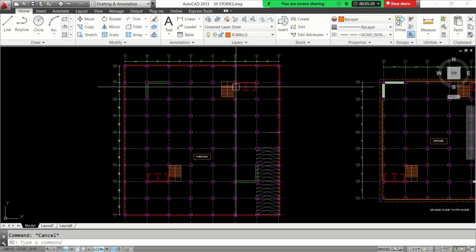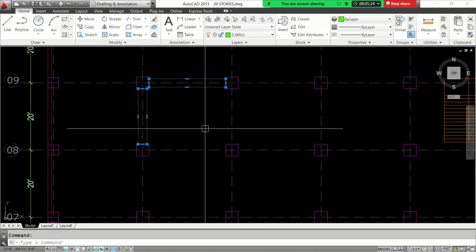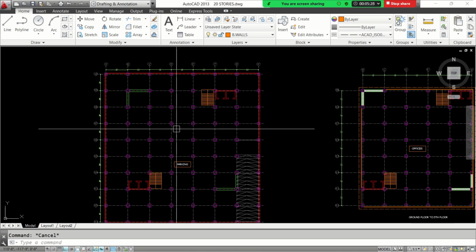But if you send these locations to the architect and he does not approve them, then you have to find an alternate solution, which is to find other locations for your shear walls, which can contribute to the structural system that will be classified as a dual system, right?